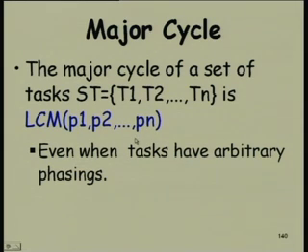No, no timer is set for the major cycle. How does the system come to know if one major cycle is over? See, it just keeps on checking the table, right. At the beginning of each frame, the timer interrupt comes, the scheduler awakes and then it tries to see what is there in the table. As soon as the table ends, it takes up the next from the beginning. The timer is set only once.